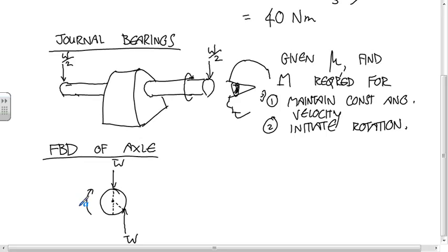Does everyone sort of follow? Yes. Okay, so it's an experimental fact that if you calculate the center of pressure of the full distributed load applied to the axle by the bearing, if it's rotating this way, you get a total bearing force that moves in such a way that it provides the opposite moment.